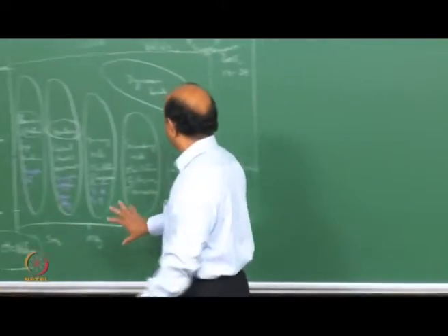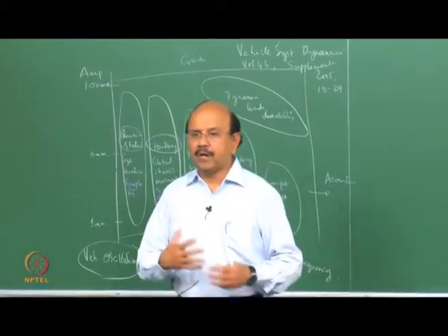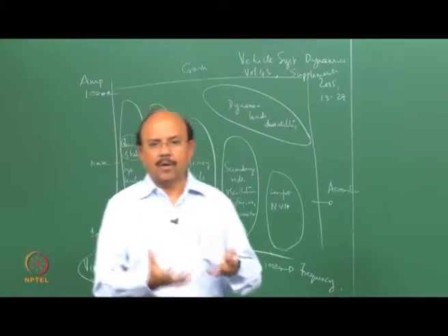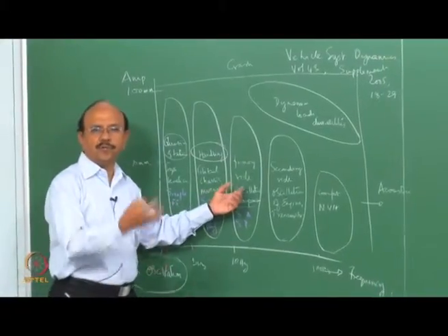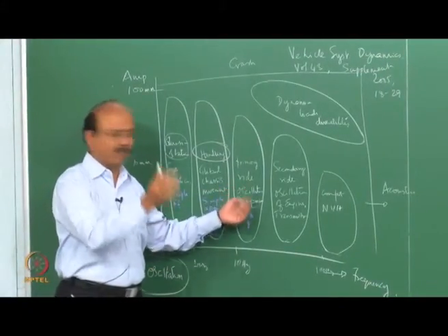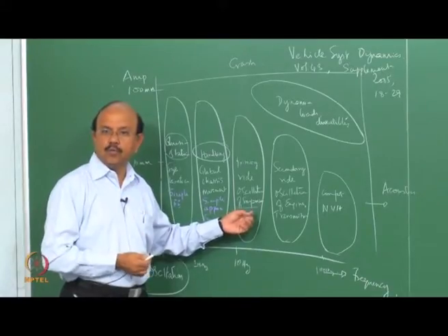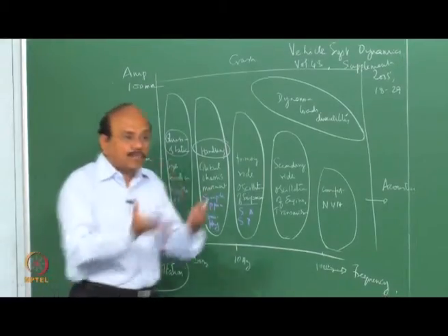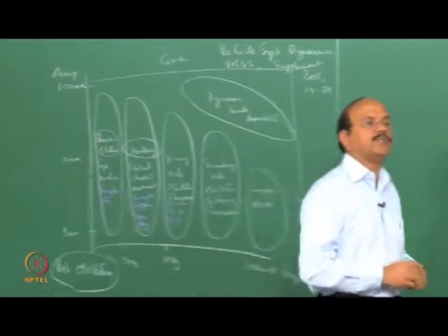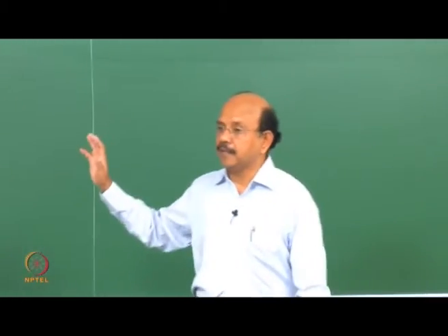But usually we look at the primary ride as one due to the oscillation of the suspension system, because of road-induced oscillations and so on. 10, 12, 14 hertz is the type of frequencies when the vehicle is subjected to these kinds of oscillations. At those frequencies, we call that the primary ride.